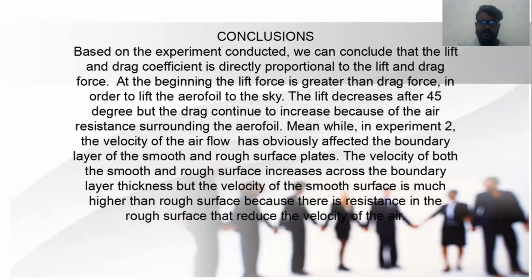The lift decreases at 45 degrees, but the drag continues to increase because of the air resistance surrounding the airfoil. Meanwhile, in experiment 2, the velocity of the airflow has been obviously affected by the boundary layer of the smooth and rough surface plates. The velocity of both the smooth and rough surfaces increases across the boundary layer thickness, but the velocity of the smooth surface is much higher than the rough surface because there is resistance in the rough surface that reduces